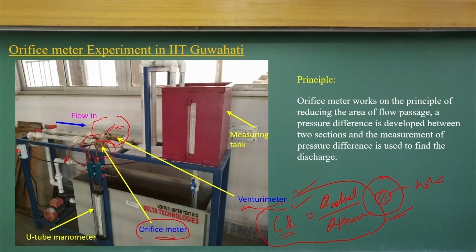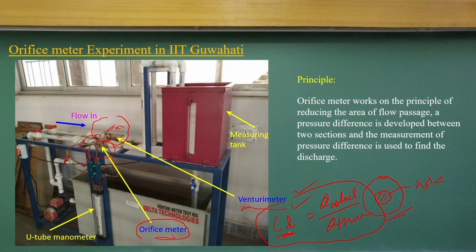So, these are gross representations of change of the flow patterns, the pressure and velocity patterns, and flow structures. We do not look at very microscopically how it is changing, but it is a gross representation. We just look at the coefficient of discharge as the relationship between the theoretical and the actual. There is a link between experimental work and analytical framework.